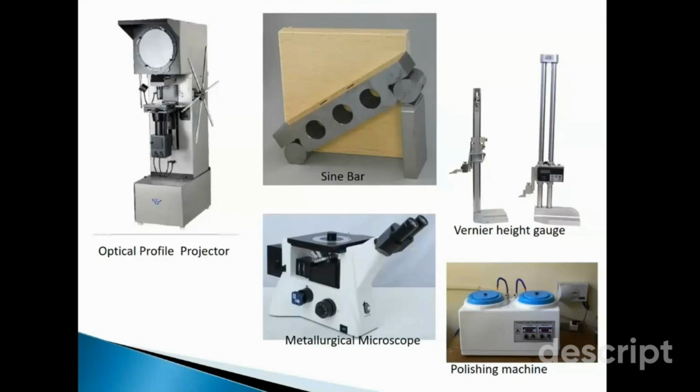This lens has a different type of magnification, and it has a removable lens, so you can change the different lenses, and it has a magnification mentioned on all these lenses. Whatever the geometry or dimension you are measuring, it will show the magnified image. With the help of a simple scale, you can measure the dimension and then divide it to get the actual dimension of a particular physical attribute.